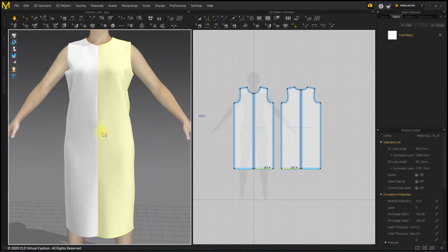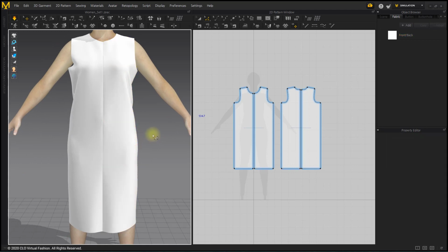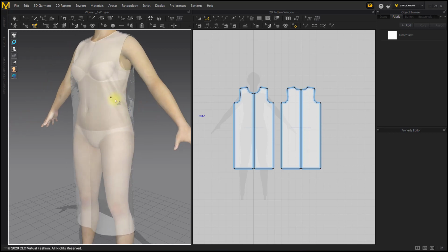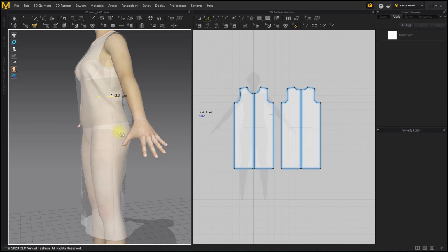Since the garment is sewn with the front and back plates, you need to make a dot and edit it at the same position on the side lines of the two patterns. Click at the waist position with the Line 3D Pattern tool to take a starting point. Then double-click to finish. Create a waistline so that the line spans the front and back panels.